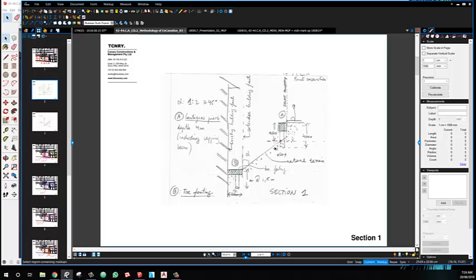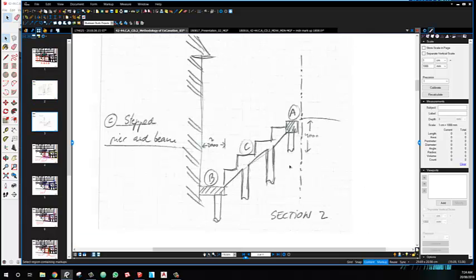Then the angle of the soil, the cutting angle at 45 degrees, and then a toe beam that will support retaining wall 3 as per your drawings, or as suggested on site, a tinsel wall with mesh on both sides. The other section is this step beam, in preparation for walls, but this has to go lower.